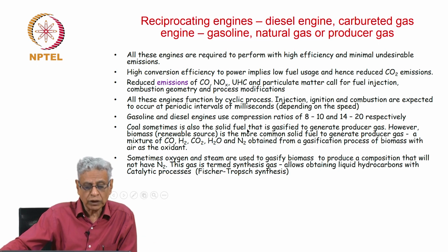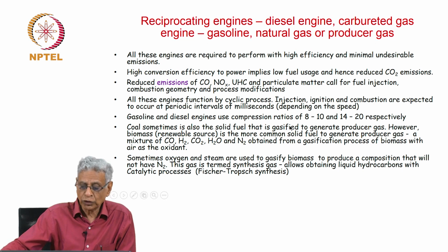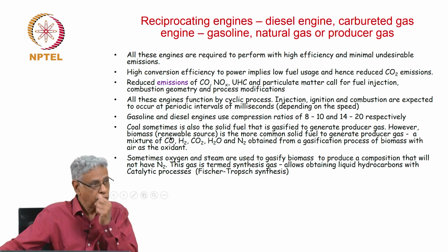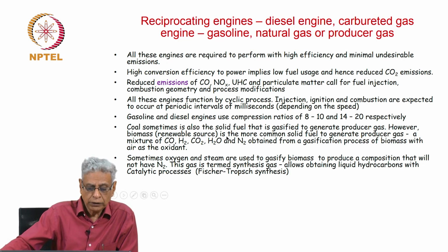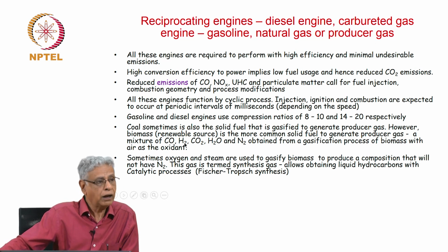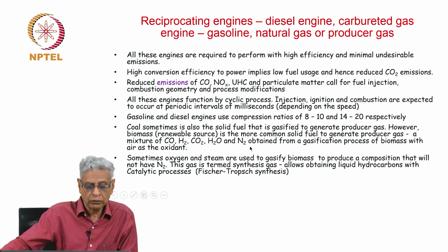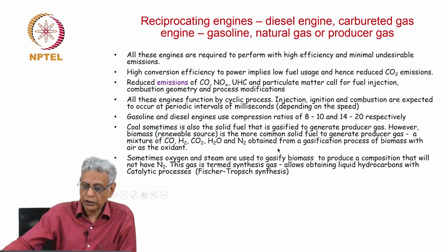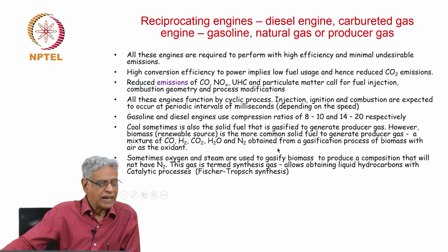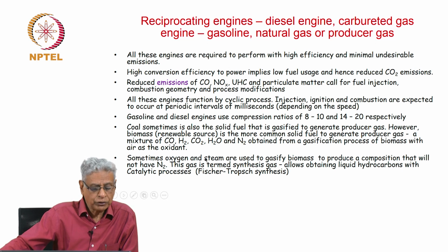Coal sometimes is also used as a solid fuel, and that is gasified to generate what is called producer gas. However, biomass, which is a renewable form of energy, is the more common solid fuel to generate producer gas. A mixture of carbon monoxide, hydrogen, carbon dioxide, water vapor and nitrogen from a process called gasification using air as the oxidant. Sometimes oxygen and steam are also used to gasify biomass to produce a composition that does not have nitrogen. This gas is termed synthesis gas.